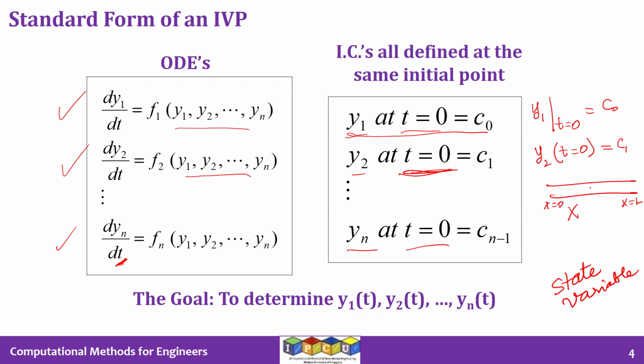So here the concentration C is the dependent variable and x, the position along the length of the reactor, is the independent variable. So we have to be given the conditions required to solve the problem at x is equal to 0 at the reactor entrance so that we can compute the concentrations at any point inside the reactor and at the exit of the reactor.